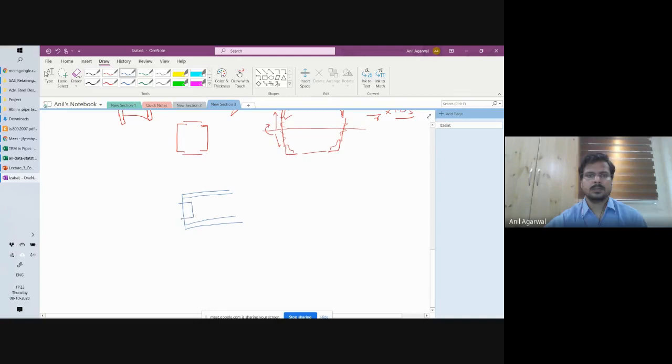Let's say this is an angle that is welded, connected to this beam, and it is connected to a column here. Now we can weld this angle to this column, and we can bolt it here. That is allowed. But what we are not allowed to do is, let's say it is welded here. That is fine. Here, let's say I calculate that my load requirement is 100 kilonewton.